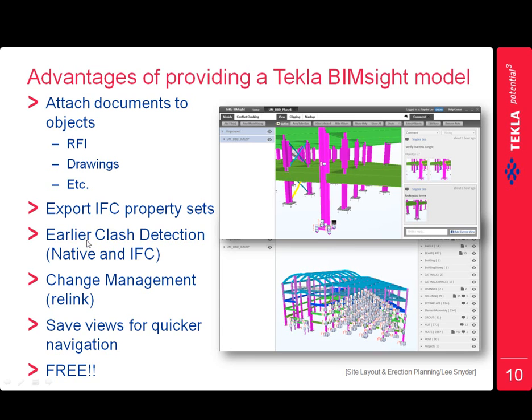You can then also run a clash detection within Tekla BIMsight, so that you can do that earlier and more often during the project life cycle. You don't have to wait for one person who has a specific license of the software to run this. You can do it yourself. The change management is really easy.